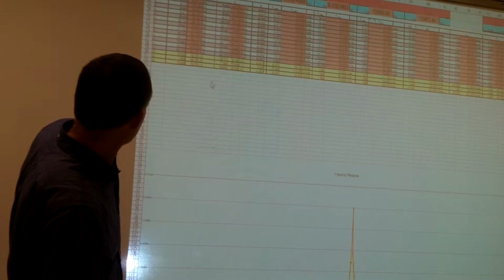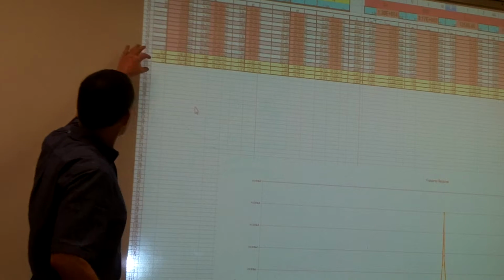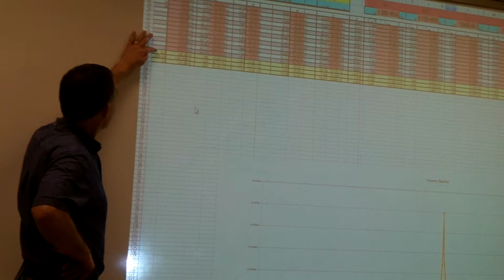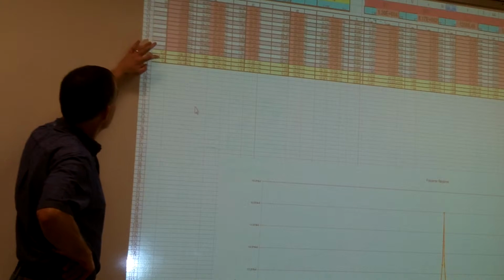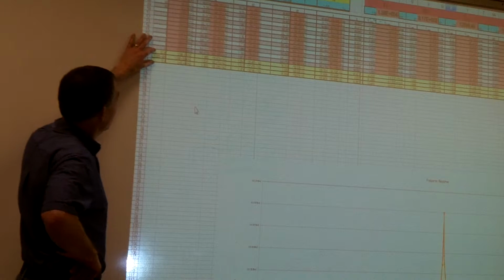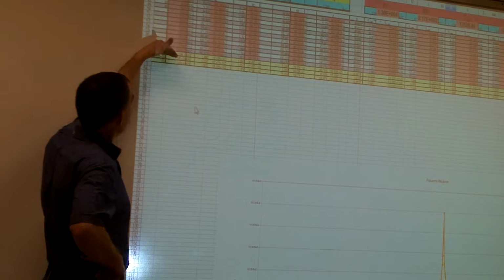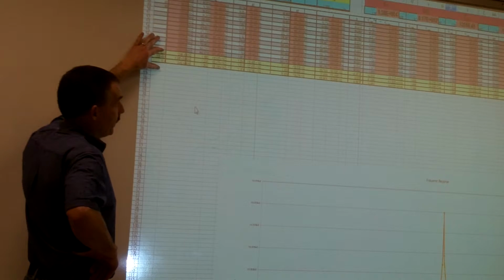the very bottom. One thing I like about Open Office is that these last 3 rows that I calculate out, I'm calculating out my lower frequency cutoff, my resonating frequency cutoff, and then my upper frequency cutoff. And I put those last 3 rows into my spreadsheet so that no matter where my resonating frequency is, I always end up recalculating that out right at the very bottom.